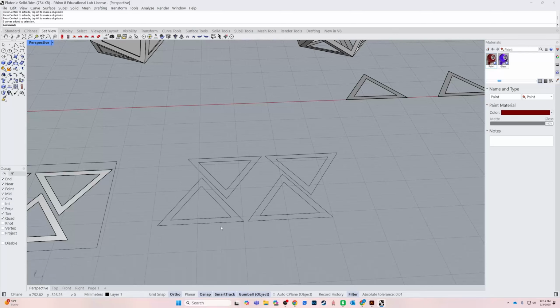So we'll laser cut out these sections. The center is fine because that can be straight. I don't mind that being straight at all. But we do need to have a little bit of extra on the cut here so that we can bring it into the bandsaw and cut the proper angle.